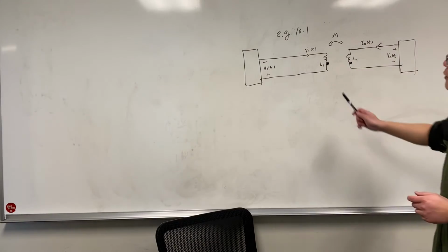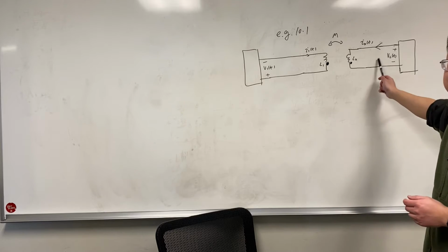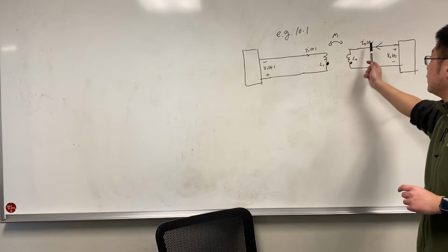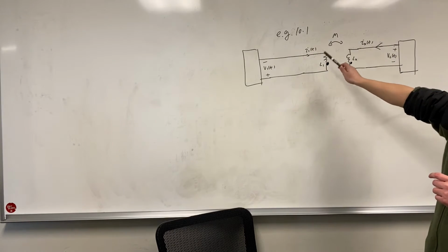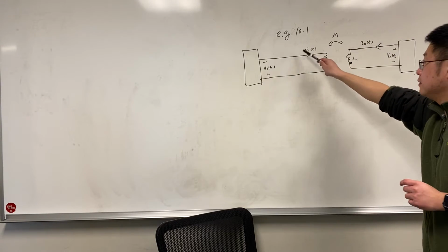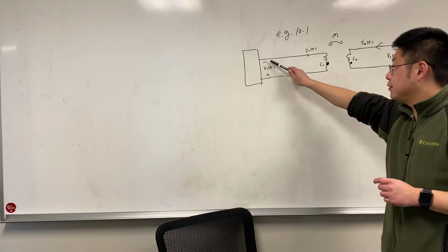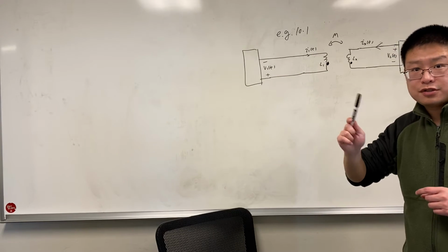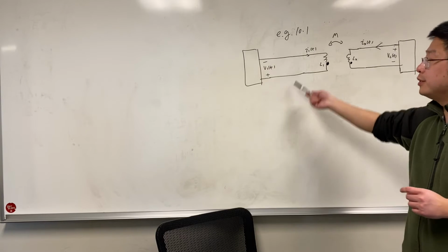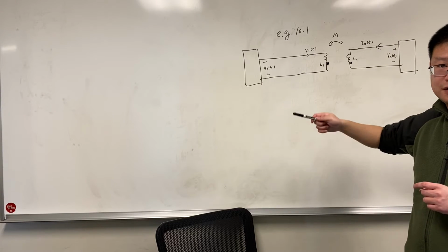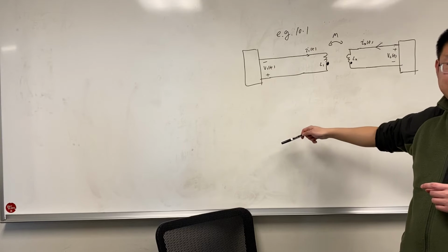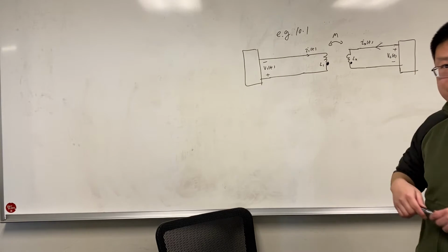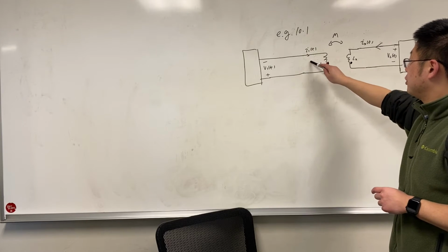Textbook. So we have the primary winding and the secondary winding, and we have the reference direction for I1 and I2. And be careful that only the arrow or the positive or negative denotes the reference direction. It is not the actual direction. We deal with the AC circuit, so it is alternating. So this is the reference direction. So let's take a look at the primary winding.